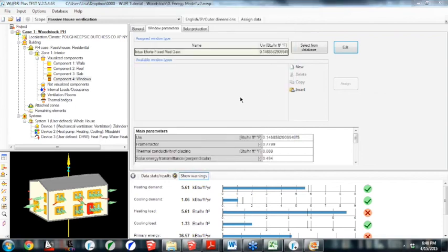What should be done on window data inputs when the door sill is not the same as the jambs and head? Same question for mullion or T-mullion multi-pane windows. You can create different window frames that have, let's say, a thinner profile where the window is mullioned. You might also be asking about the installation condition, and I didn't actually touch on that. So the psi install, where the window is installed within the wall, that doesn't occur.